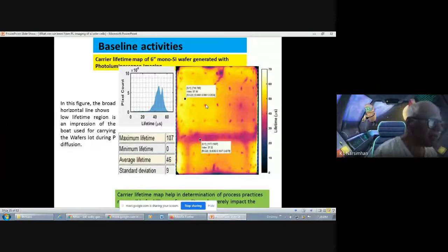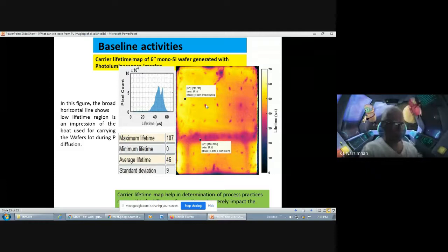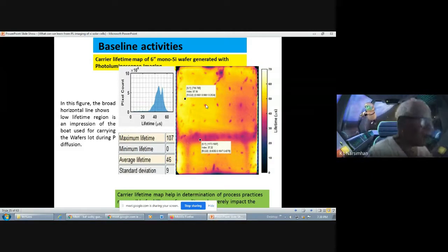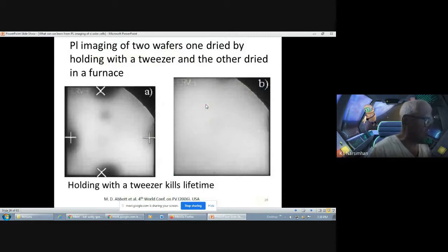So you can see that the act of making the four-probe measurement was sufficient to reduce the lifetime in those regions. There is no other way I would have actually been able to find this out. So probing the sample just tells us how careful we have to be to probe the sample. The next slide gives this in much more graphic detail.